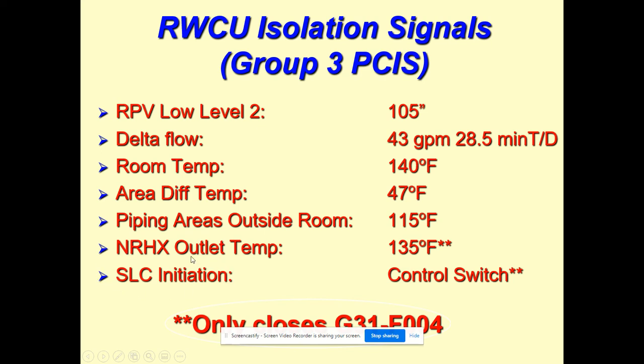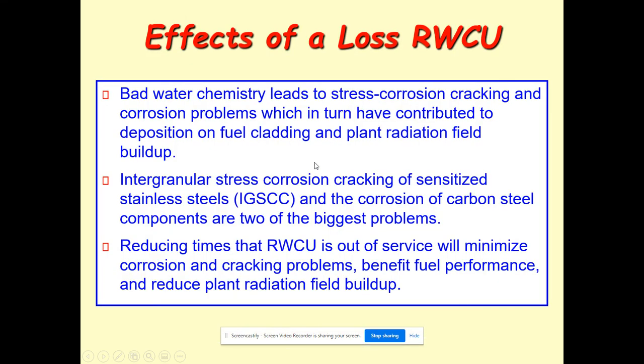And then SLC is a system we'll talk about later. It's called standby liquid control. That's the one that injects boron in an emergency. So I don't really want to be cleaning up the reactor water if I'm to the point that I need boron. So I want to make sure that if SLC, standby liquid control, comes on and I start putting boron in, I don't want to be cleaning out that boron with this system. So you can see there's a lot of interrelationships here between different systems, and then we're always looking at these temperatures to see if I have hot water or steam leaking out from the reactor into my reactor building.